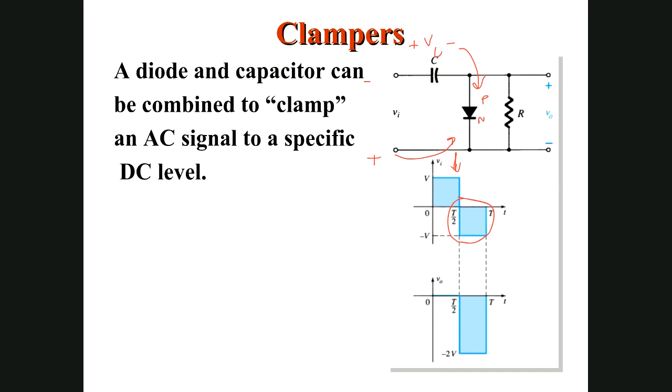So how much is the voltage? If it is an open circuit, now you have to consider this loop. Okay, and voltage in the resistor is VO. Now let us put KVL in this, and you know your voltage is how much? V. So let us write KVL. It will be plus V. Why will it be plus? Because we are starting from this point. Plus VC, and you know VC voltage is also V. We have solved it some time before. Plus VO